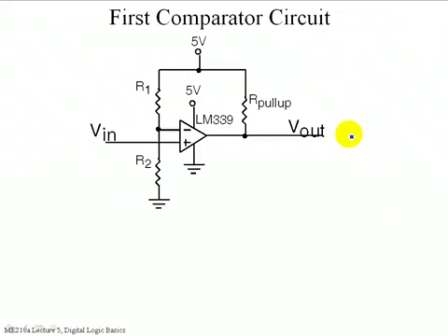Okay, so let's take a look at our first comparator circuit. So start getting used to it. LM339, actually a 139, a 239, or a 339. Those are all comparators. They all behave in more or less the same way. There's tighter quality control on the 1s than on the 2s than on the 3s. And we'll get into the non-ideals.